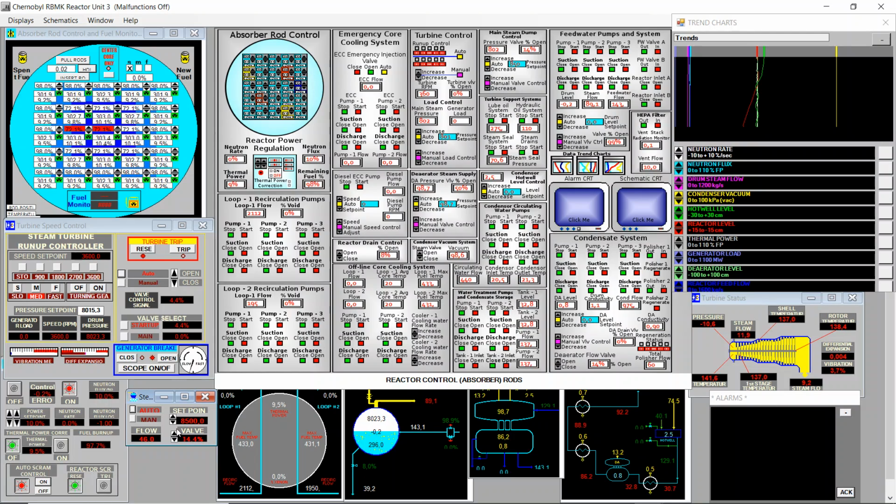So I will increase the pressure set point. Let's look at the valve opening. It should go to 0 or close to 0. Yes, it went to 0. So now I can just increase to the value I need, which is above 11,500. This is more or less the pressure needed by the turbine to be connected to the generator. So let's set it a bit above 12,000, so we don't need to waste steam by opening the waste valve.